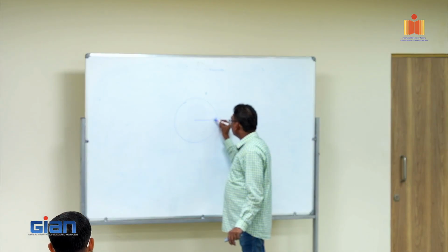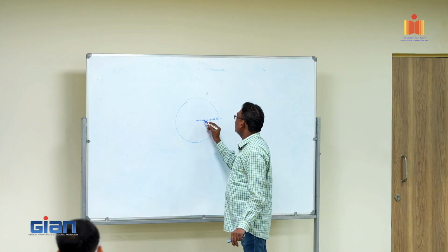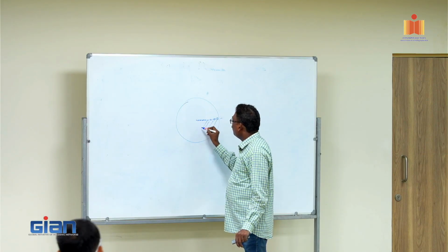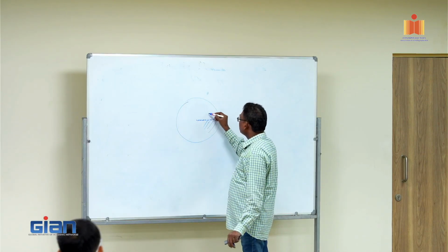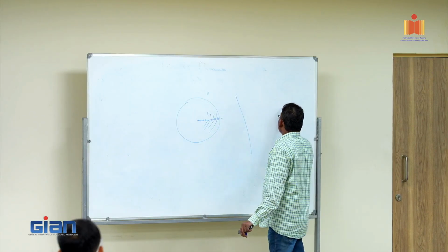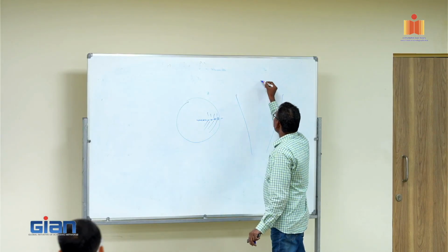We see that bigger size particles are getting settled, and very small size particles will be coming up. That means each particle will take its own radius to move around. That's the equilibrium behavior that we assume. Now the same thing, if I draw the conical section or cylindrical section, what happens is this is your central air core.